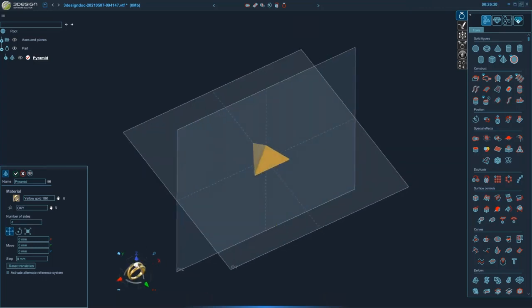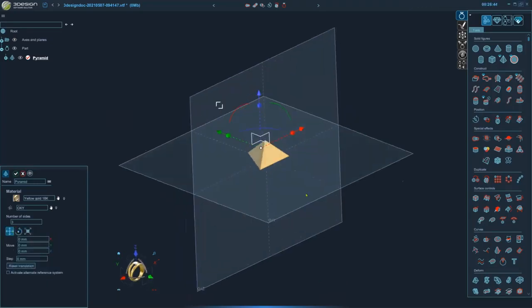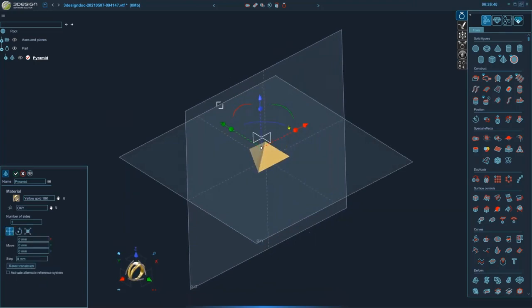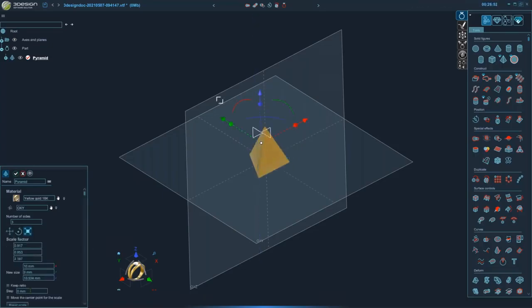So you have your pyramid shape. Very simple to use. It does have a built-in translate gizmo. So if you click on move, rotate, or scale, or any of the fields, that will show the gizmo here in the scene. So you can use it just like the regular move, rotate, scale. Including the step function if you want to fine tune how much you're moving things.